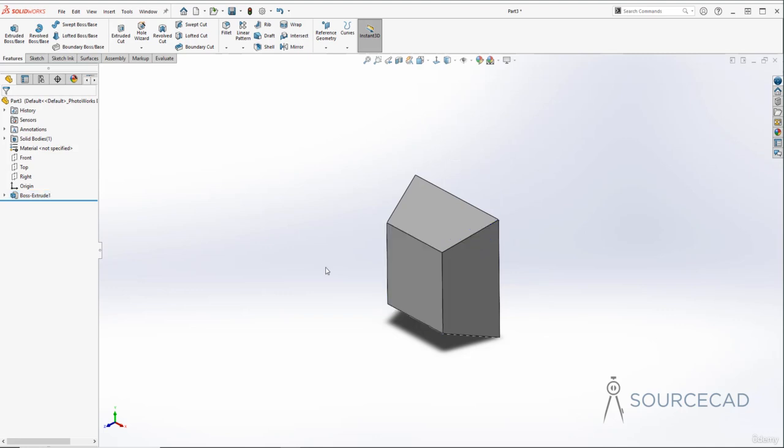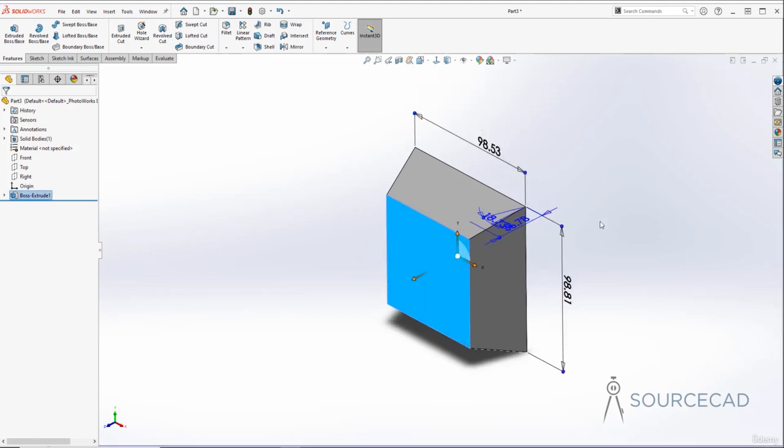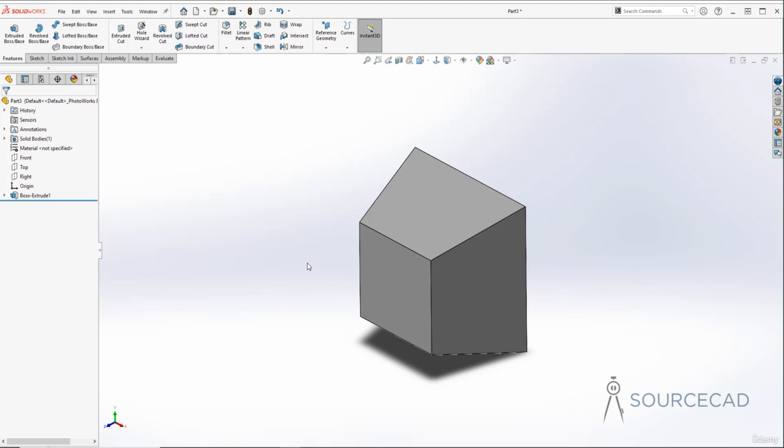Not only that, if you select any particular face, SolidWorks will highlight once again the 2D feature as well as the 3D feature, and you can use these grips to modify it even further. So this is the Instant 2D sketch feature, and as you can see, I'm still able to modify the sketch even in the 3D environment. And here, if you want to maybe change the height, you can do that here. Now that's the Instant 3D feature. So we can just make a different kind of draft angle here, and we can just make all these changes very easily from the graphic area.